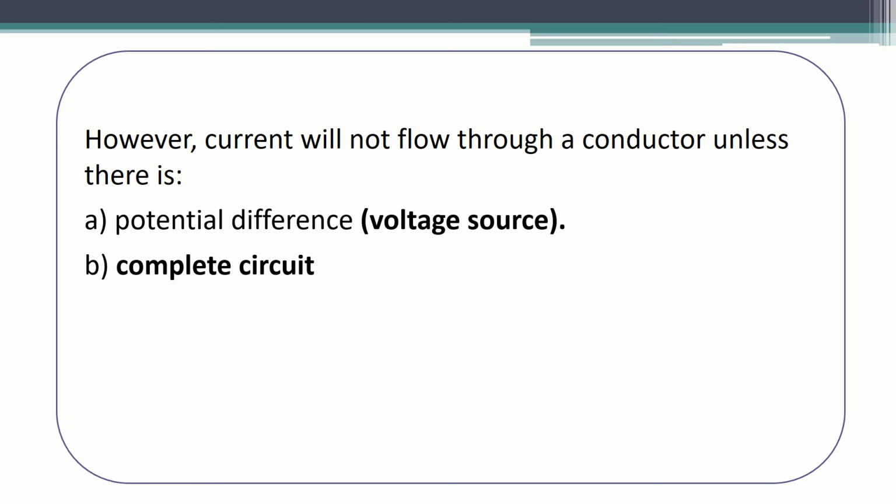So if the battery is dead, is flat, there is no voltage difference between the positive and the negative terminal. But if you have a brand new battery, let's say a AA battery, which looks something like this, right? You have your plus side, and that's your negative side, and the voltage should show as 1.5 volts. It's a brand new battery. That means that the voltage difference between the positive side and negative is 1.5 volts.